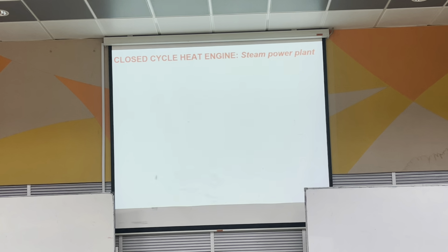Okay, so for this kind of heat engine, like I mentioned, we know that heat cannot be 100% converted into work. As you can see here also, we will have some Q out. So we need to define the efficiency of this kind of heat engine. So what we use is the term we call thermal efficiency. Thermal efficiency, how efficient is the thermal energy? Of course, the way efficiency works, the equation is still very standard: desired output over the required input.